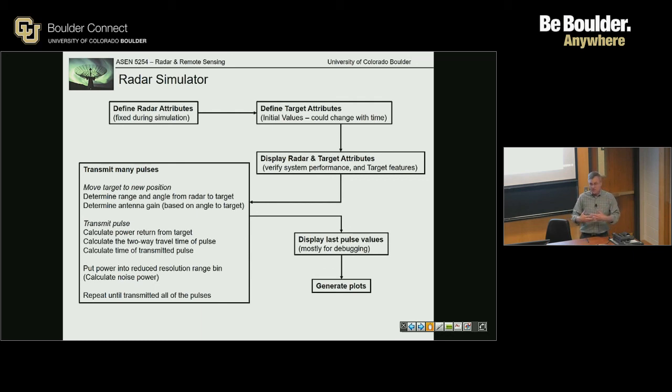Because when someone says, I have a 3 dB change, what does that mean? A doubling of power. You don't know if it's in the transmitter, the antenna, or the target. And in some cases, it doesn't matter. The antenna's fixed, the power's fixed, now the target has changed by 3 dB. Well, the target had to change. Or someone says, I want to spend more money and buy a bigger transmitter. Now you do a cost trade-off of more power. Is it worth the dollars? How much gain are you going to get? It might be more cost beneficial to increase the gain of the antenna.